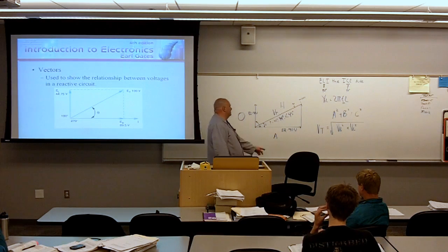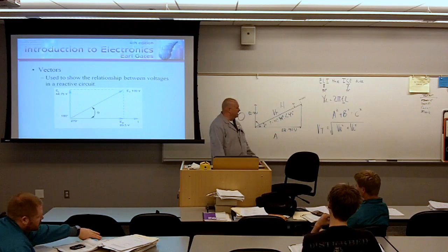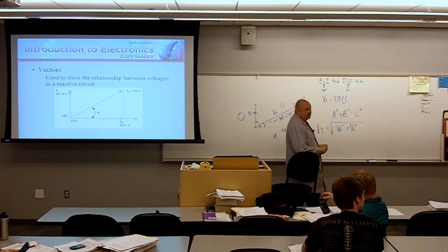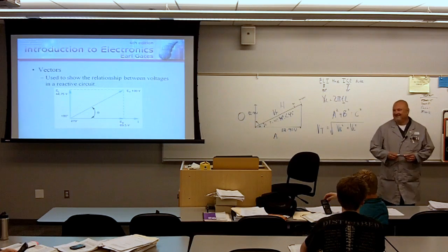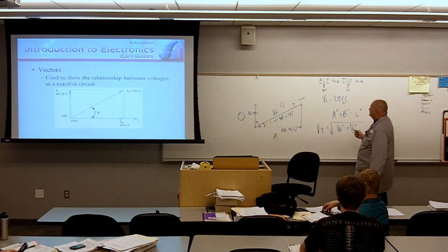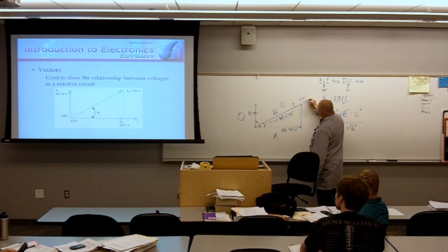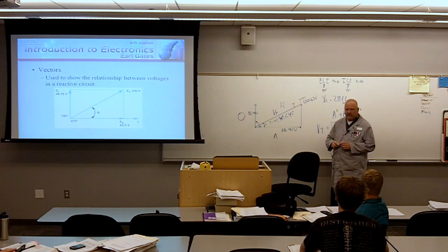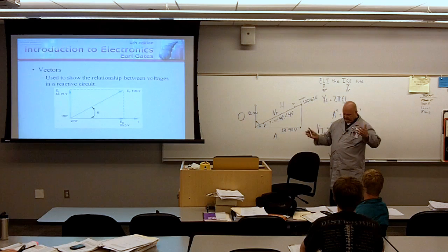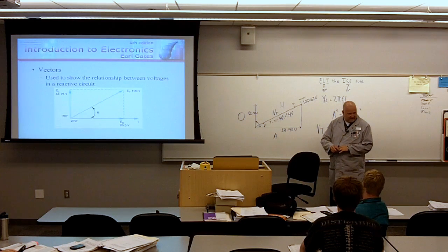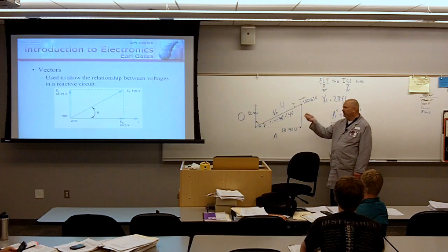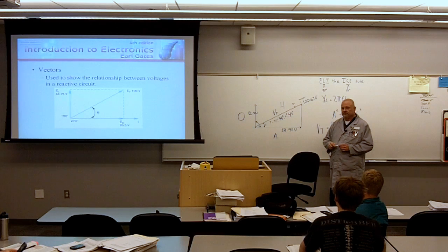So why don't you go ahead in your calculator, use my numbers. Don't use the numbers on the board, use my numbers. What do you come up with? 100.62 volts. Peak, RMS? Considered to be RMS unless otherwise specified. And if it's not RMS, convert it into RMS and then perform the math, because you should always be dealing with RMS when you're dealing with this. Make sense? Everybody get that number?